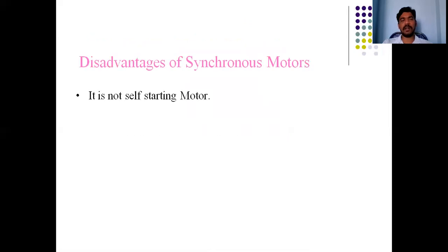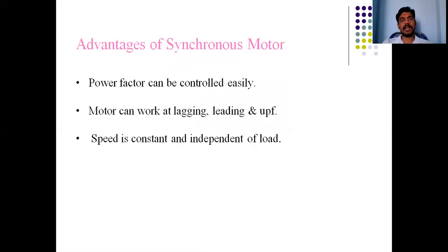Advantage of synchronous motor. The very great advantage of the synchronous motor is that the power factor can be controlled easily. We can run the synchronous motor at a lagging power factor, a leading power factor, or unity power factor.